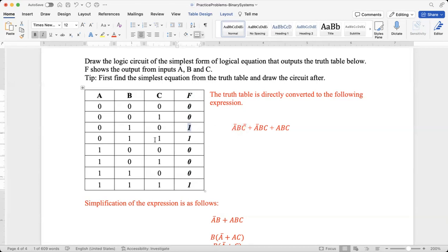The second line is here. As you can see, we have 1, 0 here. We have a 0 here, and that's the only thing in this line that we are going to need to inverse, which means we are going to have an OR in between, and we are going to write the second expression.